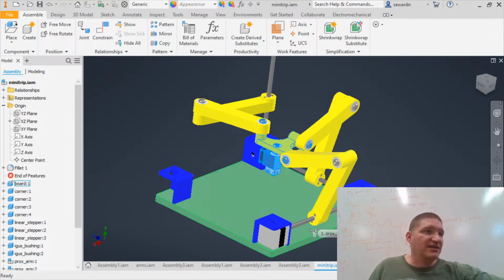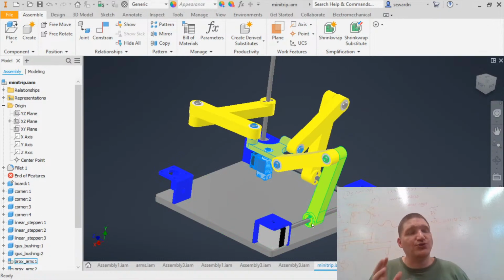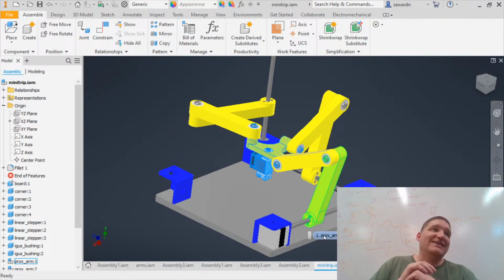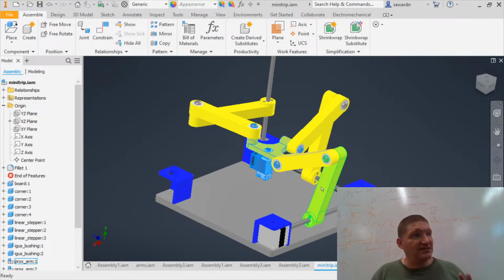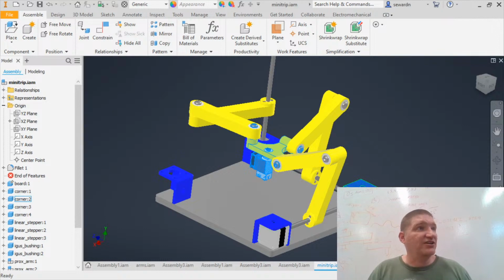And this is not a Tripteron. I'm going to call it a Tripteron, but it's not a Tripteron because whenever one of the other axes moves, it will actually change my position on the screw and mess my position up. That makes the math oh so hard. So I actually need to have knowledge at all times about where my arms are in space so I can calculate the right things. For the simplicity of just having everything on a screw, I have to pay for that with some firmware. I think I can pull it off. I think it'll be a super fun little project. Like who doesn't love a little cute printer? I'm sure somebody.